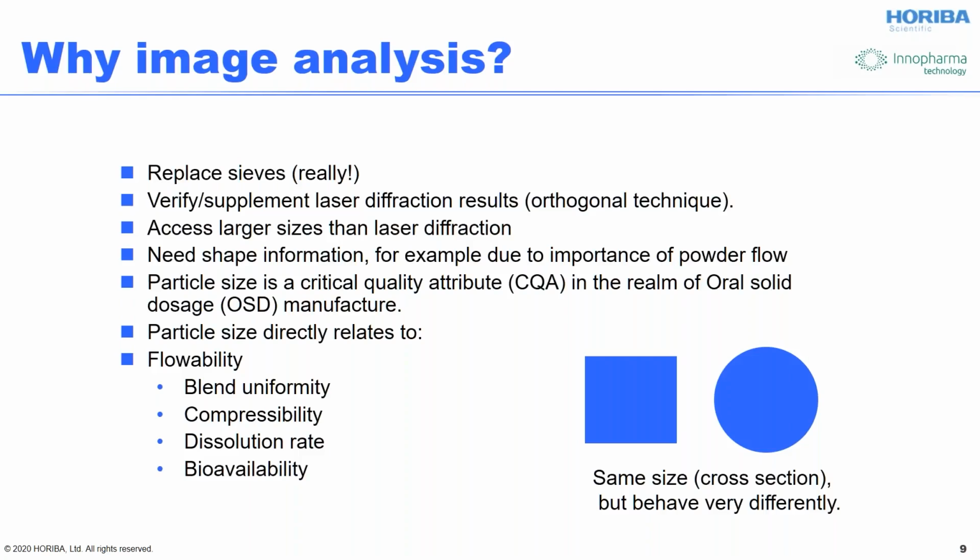You can get to larger sizes than you can by laser diffraction. If you need shape information, for example, if you're thinking about powder flow, I might have my spheres and my cubes, and they'll have exactly the same cross-sectional size, but they'll behave quite differently as you try to flow them or pack them.